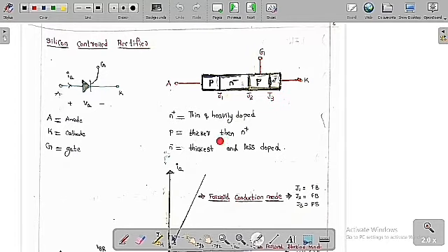Whereas P is thicker than N plus, meaning its width is very high, but the N plus width is very small. N minus is the thickest and lightly doped; its width is very high and it is less doped. So this one is very thin but heavily doped, this one is thicker than N plus but normally doped, whereas this one is very thick compared to everyone, but lightly doped.